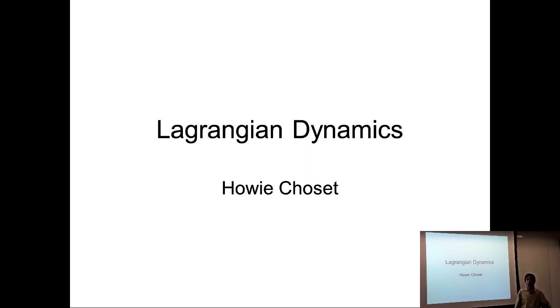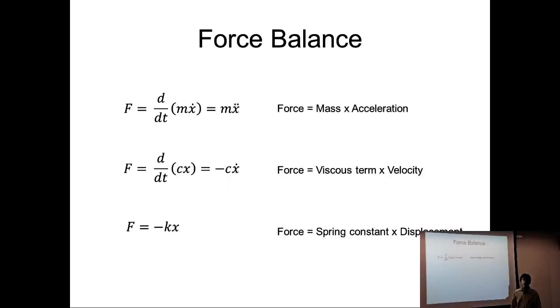In the last lecture, we started to talk about forces, that's statics, and there we were able to relate the force and moment of the end effector to the forces and torques on the joint variables through the transpose of the Jacobian. Here, we're now going to start worrying about the accelerations, and we'll bring in the force relationships through the Jacobian at the end of the lecture. Now let's look at some force balances.